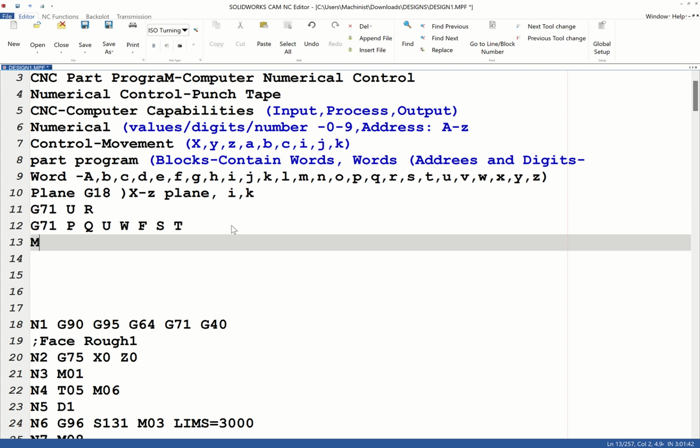Where am I starting with? Maybe I can now say M03, M3, S1800, and a feed rate of, for example, 40, if I'm using G94. G94, 40. If I'm using 0.1, I'm using G95. So this allows you to denote the program if you're using turning. These are called canned cycles. A canned cycle is a program that helps you simplify the program so that we don't write a long program. In Siemens, you're using cycle 95, cycle 94, cycle 71, depending on the controller you are using.